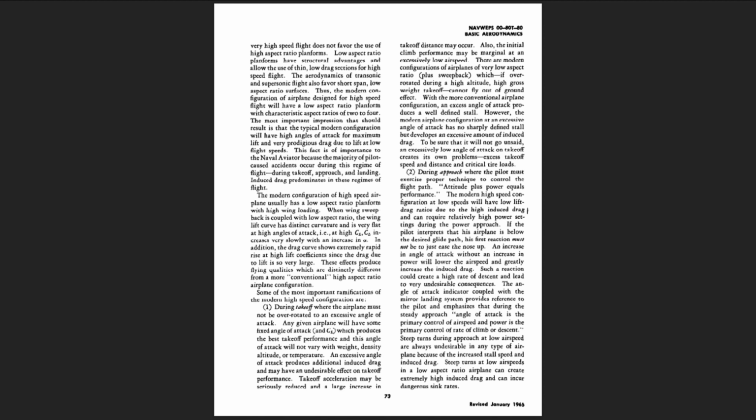When wing sweepback is coupled with low aspect ratio, the wing lift curve has distinct curvature and is very flat at high angles of attack, i.e., at high C_L, C_L increases very slowly with an increase in lowercase alpha. In addition, the drag curve shows an extremely rapid rise at high lift coefficient since the drag due to lift is very large. These effects produce flying qualities which are distinctly different from a more conventional, high aspect ratio airplane configuration. Some of the most important ramifications of the modern high-speed configuration are: 1.